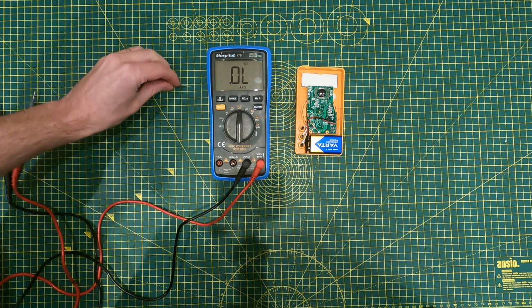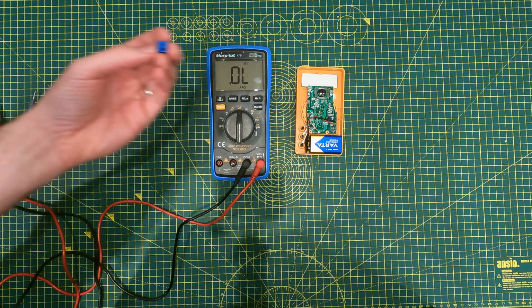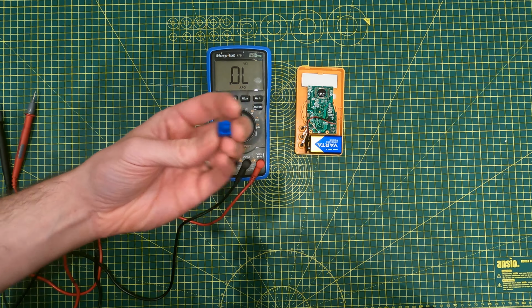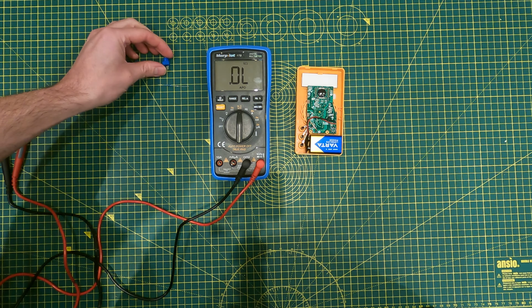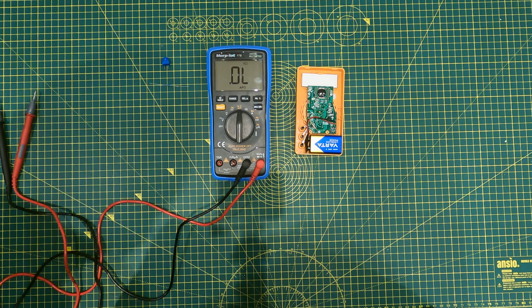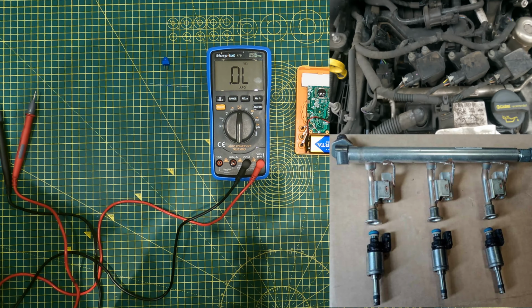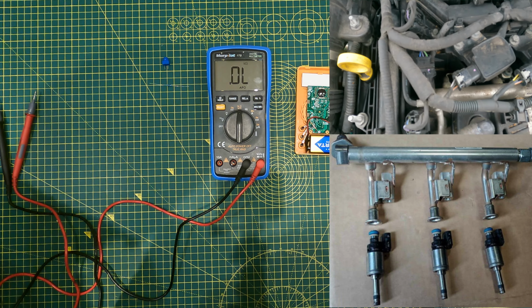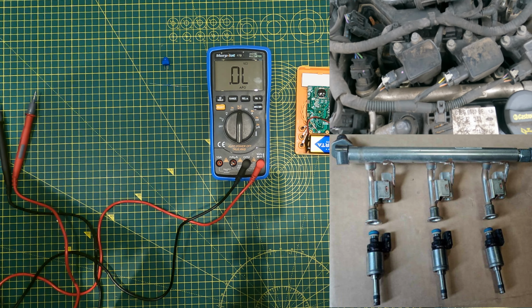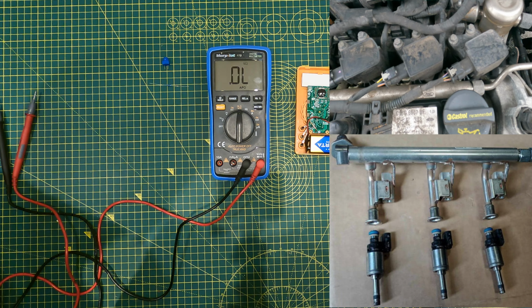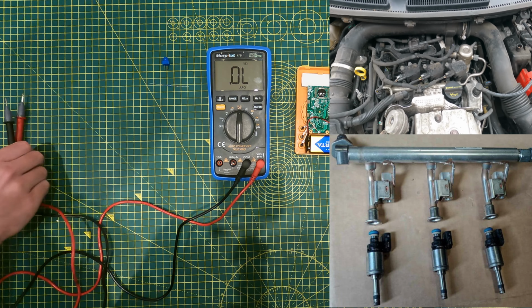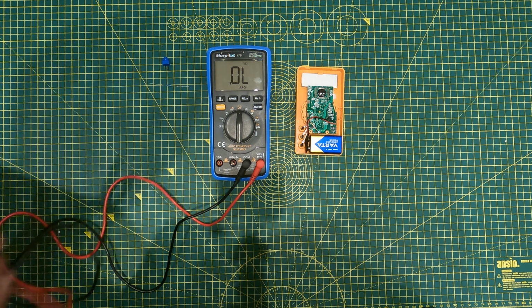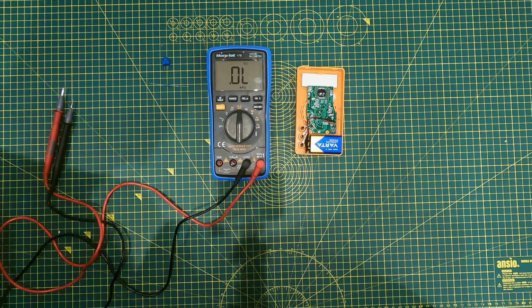You can also measure things like potentiometers, and there's other things like injectors on your car. That's a good practical example actually. If you measure the resistance and it's not within a tolerance, you know the injector's bad and you need a new one. There's many other things you can do measuring resistance that come in handy. So that is just a few examples of why resistance is useful to measure. Let's now move on to our next feature.